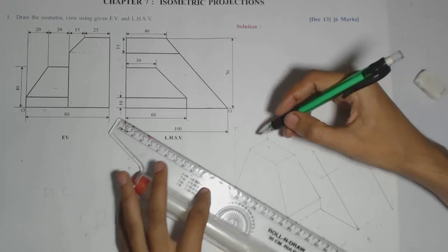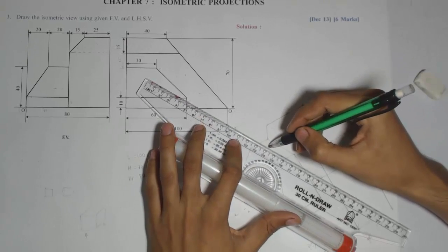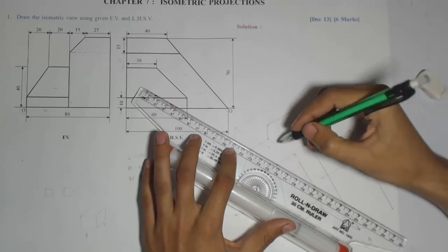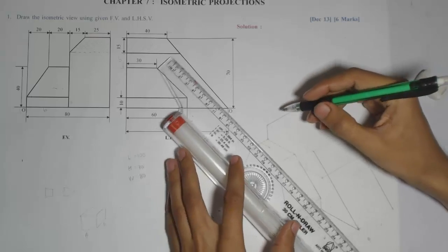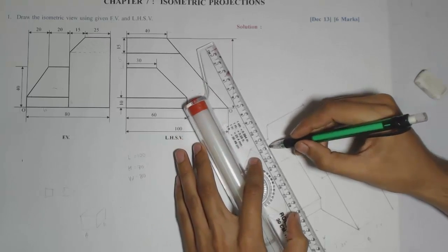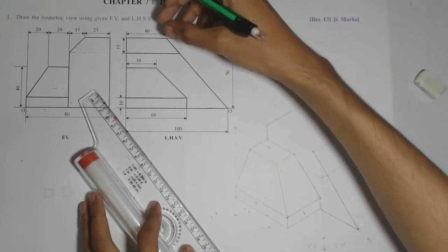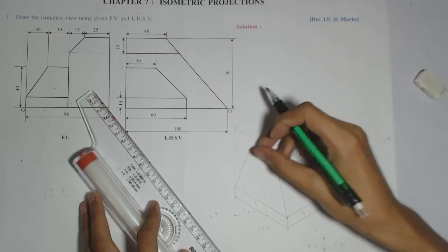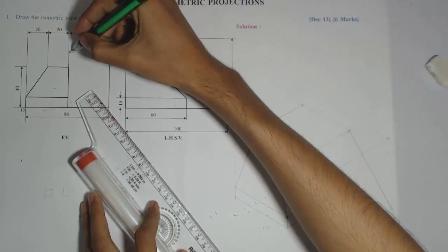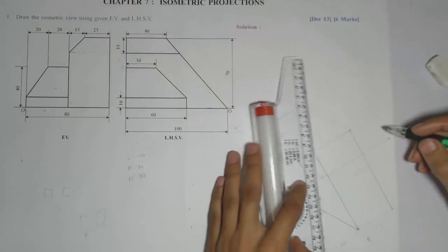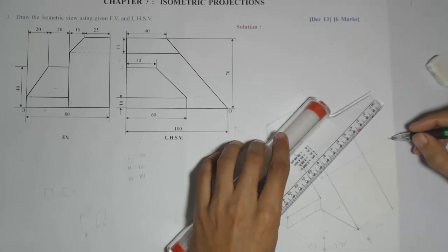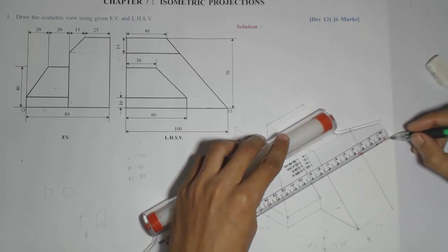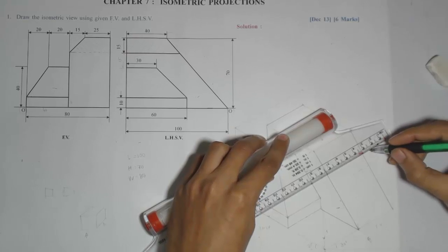Now moving to the next part, which is this trapezium, this one. Which is representing the remaining height in the left hand side with this part. Again corresponding, we have made one closed, again a trapezium. So for that I need to measure this 25 mm from this boundary of the rectangle. So I'll measure first 25 mm to draw that inclined line.